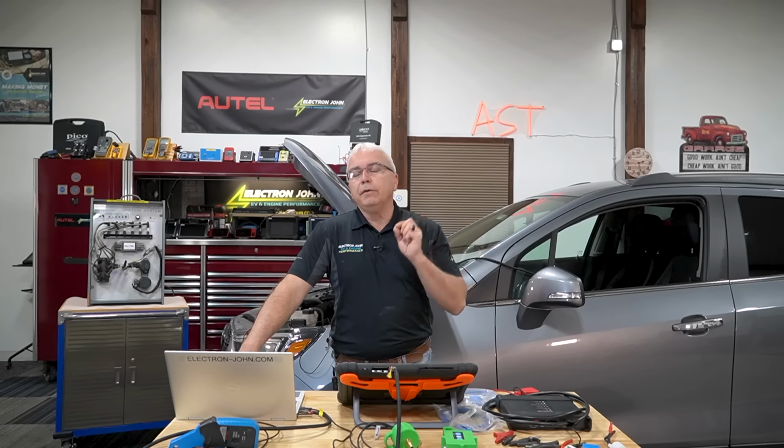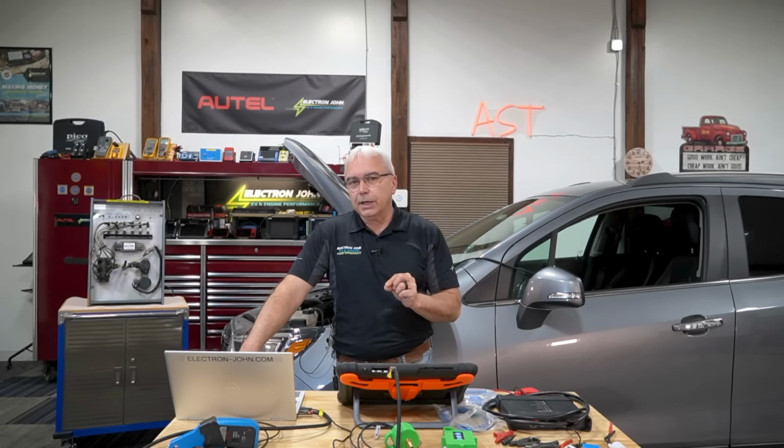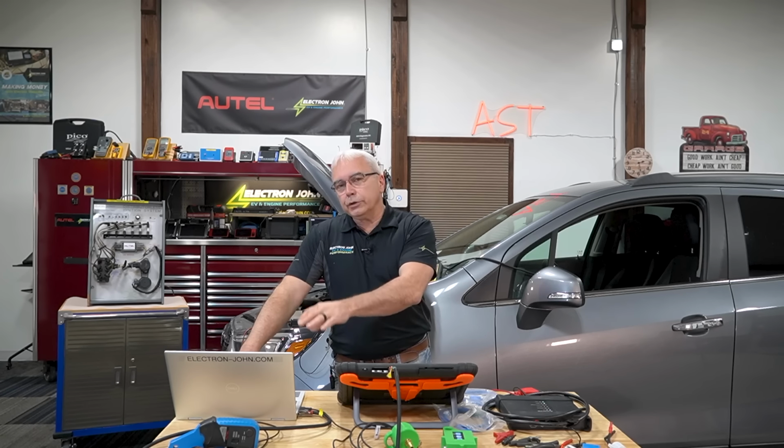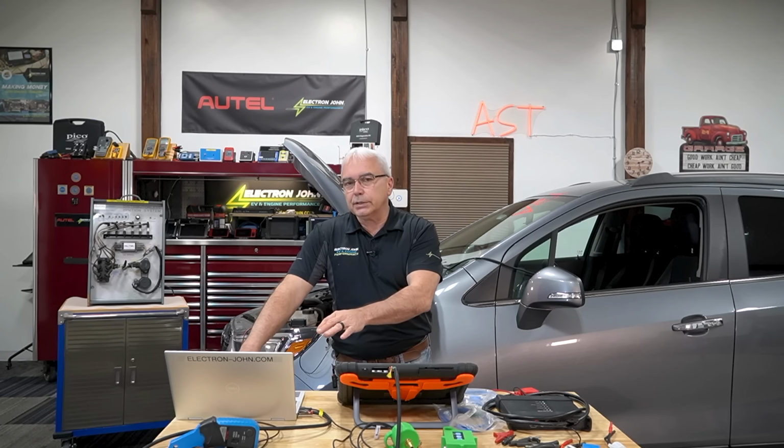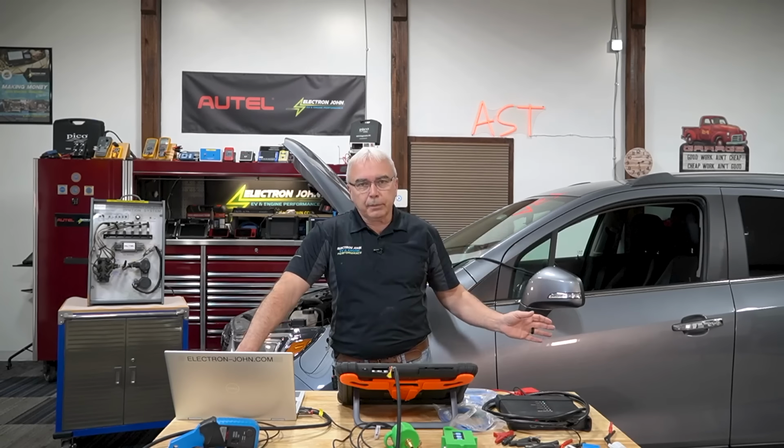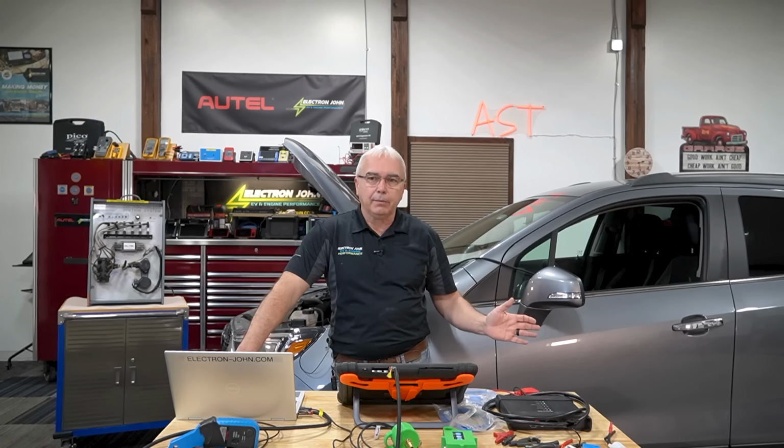Because if it was a gross leak that was failing the large leak test, the small leak test, and the different phases that Ford had there, then you could justify that it could be that the gas cap's missing or the gas cap's bad or whatever. But if it was a small leak test and you saw that it was done under certain drivability conditions, then that would rule out the possibility of a bad gas cap.